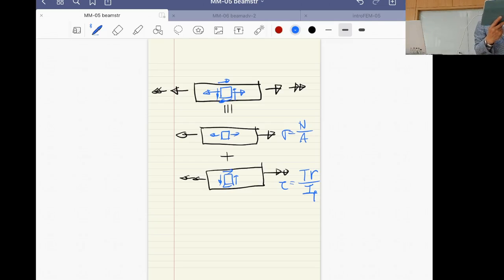Have you ever heard about load cases? I wonder, are there any fourth-year students? Okay, if you study design, if you take design courses, you discuss the concept of load cases. So we consider individual load cases, and then we superpose the load cases to obtain the various combinations of load. The principle of superposition is widely used even in actual, real engineering practice.